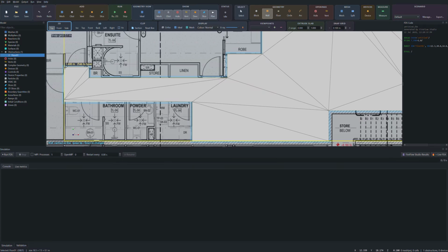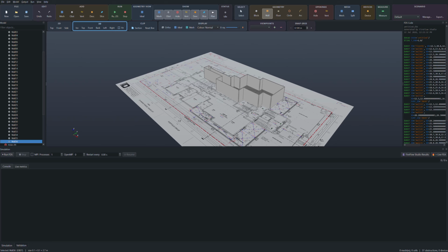Now what you will notice is if I press up, it'll align it internally. If I press down, it's centrally aligned, and if I press down again, it's externally aligned. So let's align it internally and complete the line. Let's put a height of 2.7 meters, thickness of 0.1 and create. Now I've got a 3D model just like that.